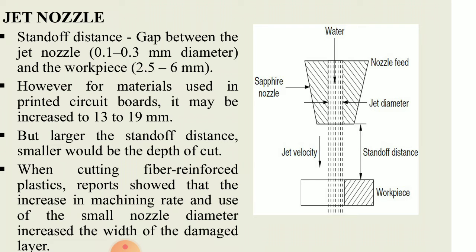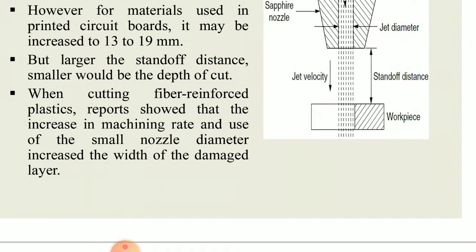When cutting fiber reinforced plastics, reports showed that the increase in machining rate and use of the smaller nozzle diameter increase the width of the damage level. Okay, so while performing machining or cutting drilling operation over the plastic material, you must keep certain precautionary measures.